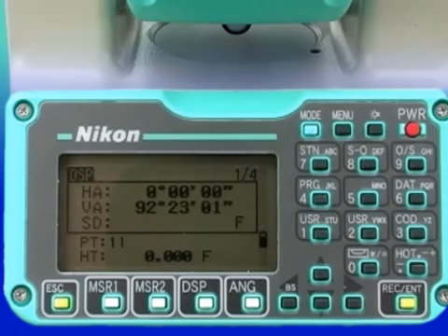The total station is now ready to measure and record points referenced to a known grid with a known orientation. It is now possible to dismantle the instrument and reinstall it at this point, and knowing the backsight, be able to re-establish the total station relative to this grid in 3 dimensions.